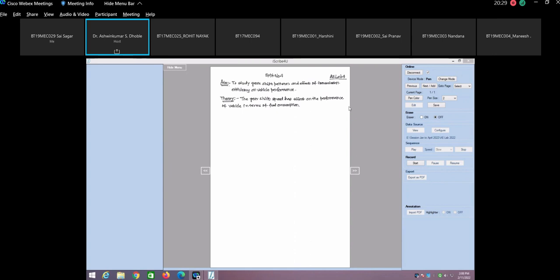So for achieving, let us say you are changing the gear from second to third at the speed of, let us say, 35 or 30, then in that case, to achieve the same 30 kilometer per hour of speed, you will have to pump more amount of the fuel into the engine combustion chamber, because the transmission efficiency will shift the RPM from lower side to higher side. So that is how your fuel consumption goes down.